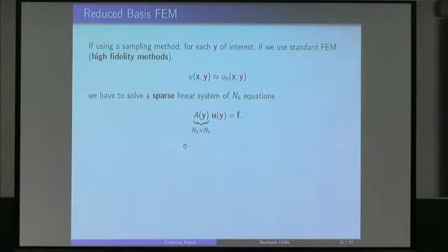So what happens if you use a standard finite element method? And again, just to stress the importance of language, in this community, this term is often used, high fidelity method. High fidelity means you've got good accuracy. So if you want to apply a standard finite element method, here's your solution to your PDE again. This is a thing that you never have. In the standard method, you're going to approximate the solution by choosing a finite element mesh. So we have our h here. For each choice of samples that you might be interested in, so if you're doing Monte Carlo, you're going to generate samples of these things.